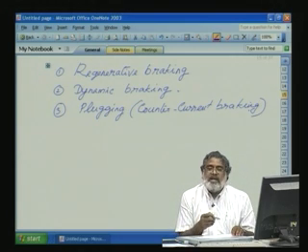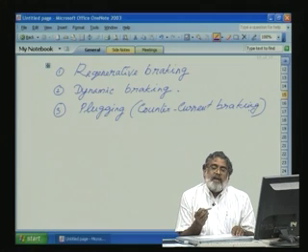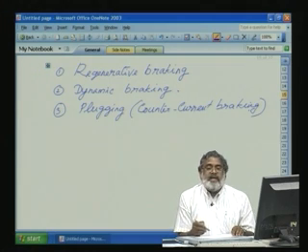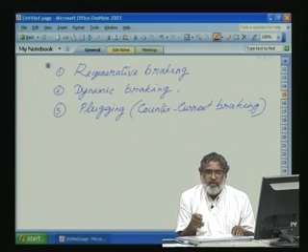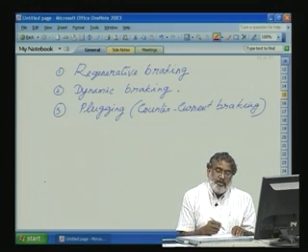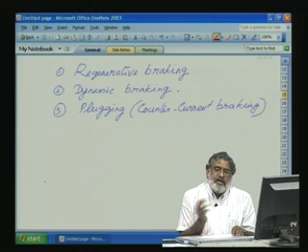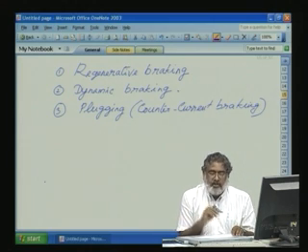That means here alpha should be 180 degrees. That firing angle, the phase shift between the input current and the input voltage, should be 180 degrees. So, power will be going from the load side to the source.